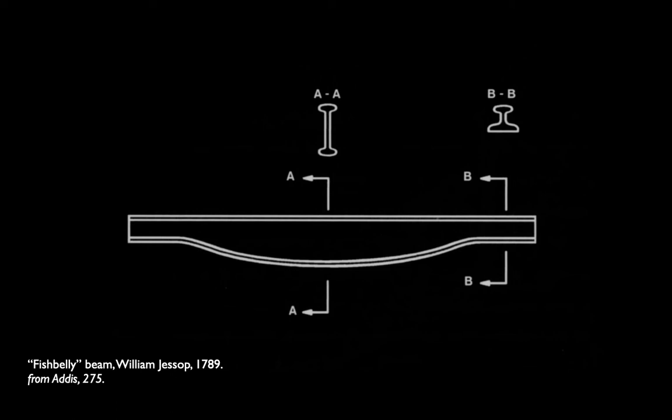Taking advantage of the emerging science of that shear and moment diagram to build a beam where the material is deployed exactly where it needs to be. Now, the other cool thing about this one is look at the cross section, right? AA and BB. They are starting to realize that the I-beam, today's W shape, the flange and web combination, is the secret to making iron beams that work really, really efficiently.